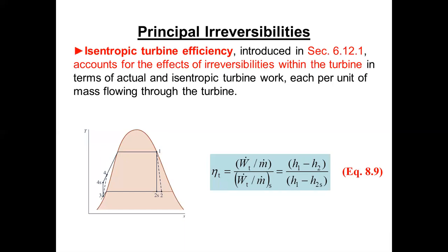And so point 2 can slide back and forth a little bit on that isobar line of constant pressure, where you have to stop because you're saying we're going to come out at the same pressure. If I have a better turbine, then I will approach a vertical line straight down. As you move along that line to the left, the enthalpy gets less and less because you have less steam and more liquid, and so you get more work out. So the maximum possible work out is in the denominator, h1 minus h2s. Okay, and so I think all that pretty well follows.